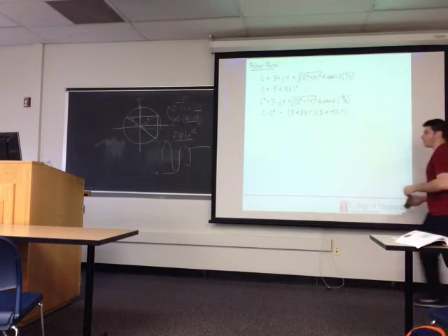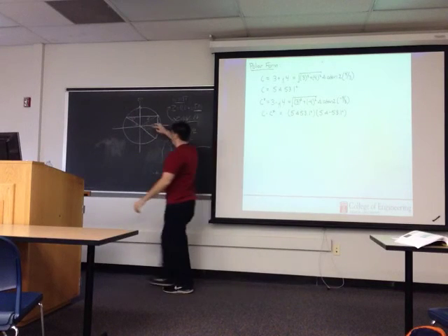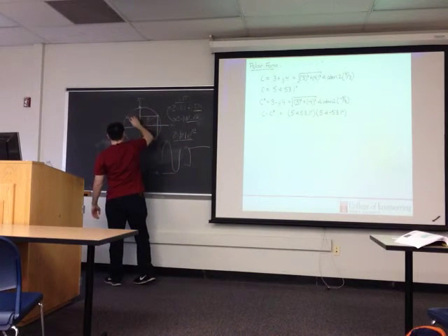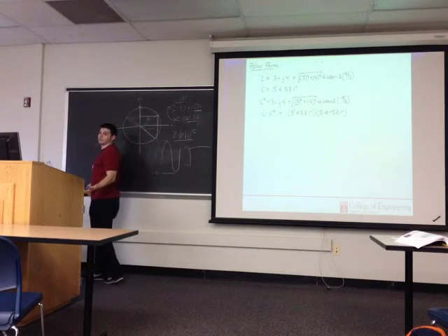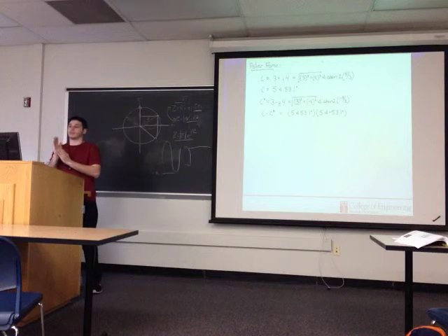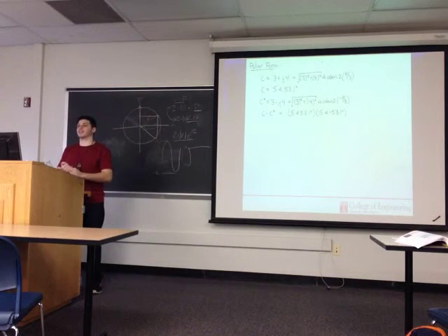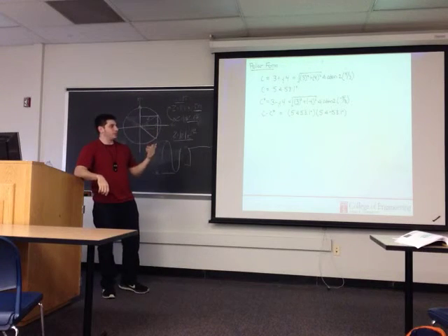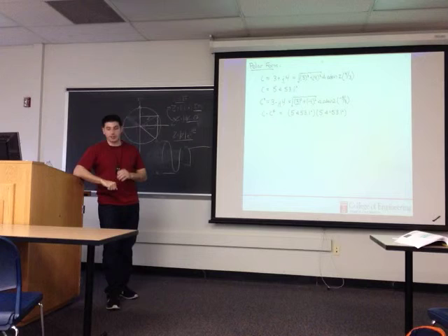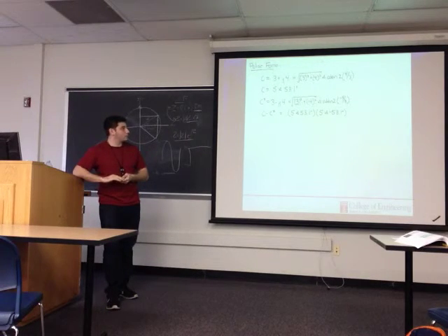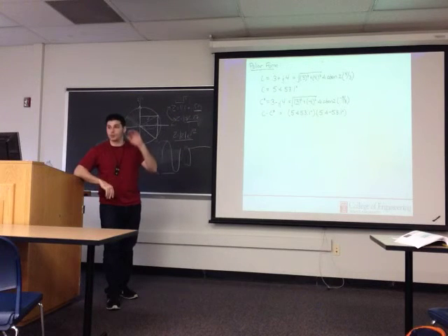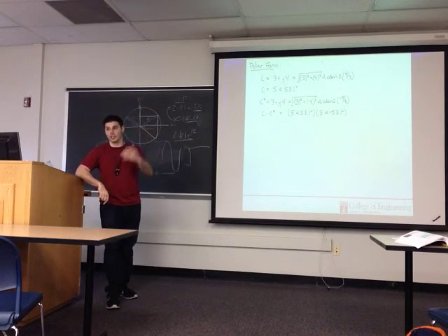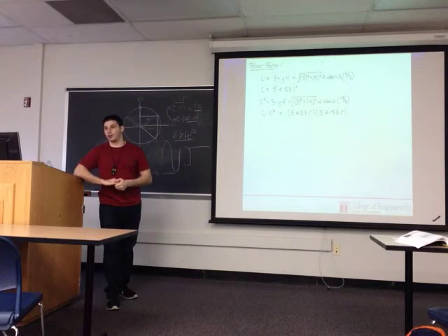Would you ever not use things that come in the imaginary part? Yeah, I guess resistance, because resistance is just real. But we're working on impedance, right? We're working on impedance, exactly. Is the J portion always going to be on top of the inverse tangent? Yes, your imaginary part, or your J coefficient, is always going to be on the top of your inverse tangent.